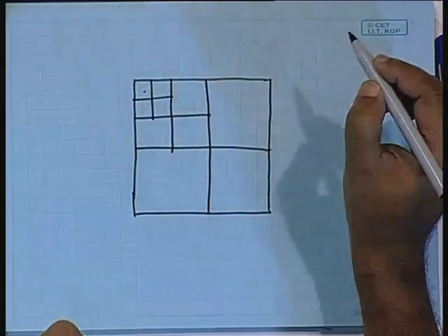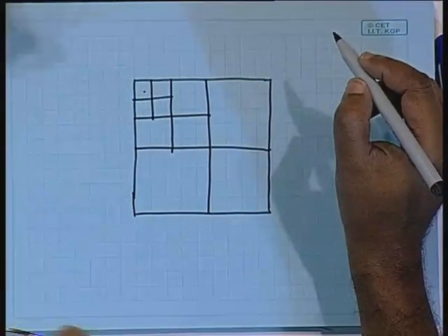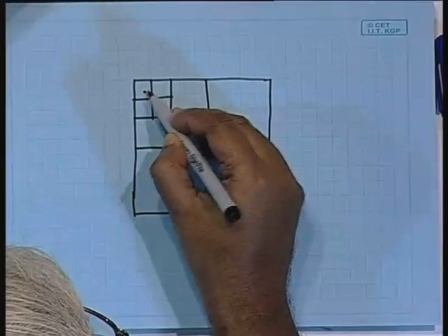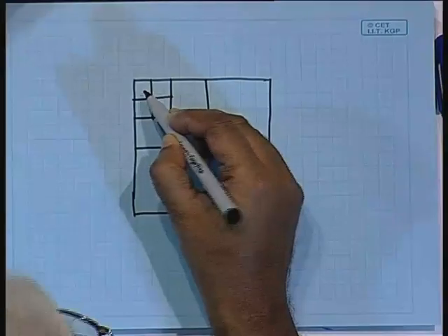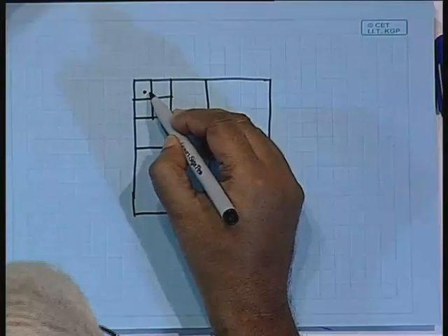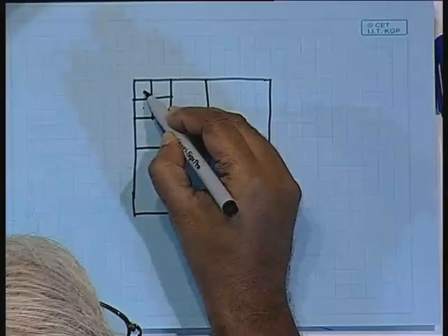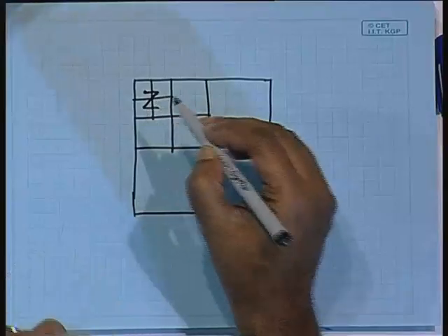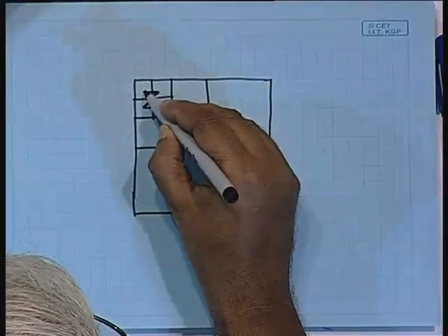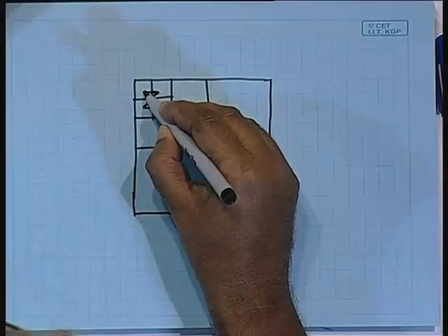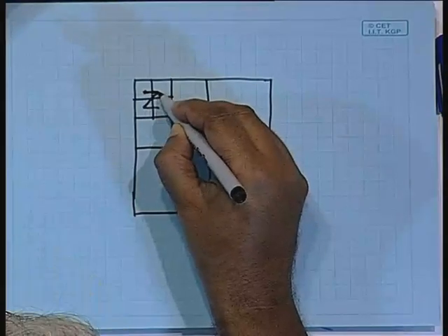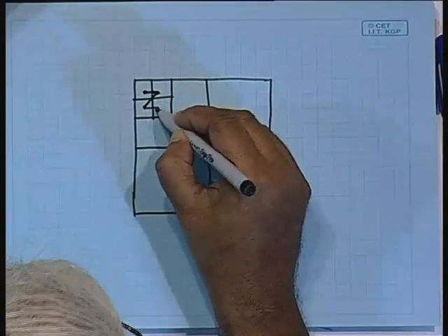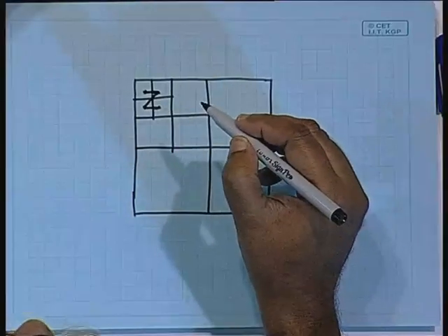So, what we do is that we pick up the coefficients from the topmost LL subband, which is this one, and then we form a tree where the descendants would be first the HL, LH and HH coefficients in the same resolution, and we will be picking up those coefficients in this order. That means to say that first start with this as the root node, go over to this, explore this, pick up the corresponding coefficient in this subband, pick up the corresponding coefficient in the next subband.